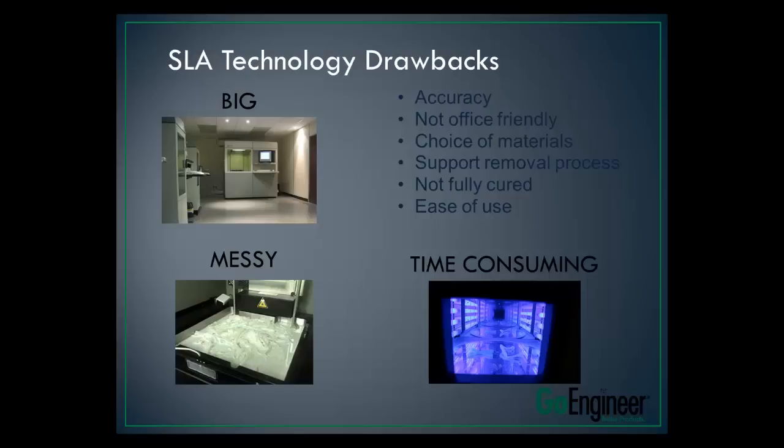The machine holds gallons of this resin at any given time, and the resin is pretty caustic, and it's really messy. It's about the consistency of a light syrup, and the leftover resin has to be disposed of according to EPA regulations. You have to fully cure it. If not, it's all hazmat.